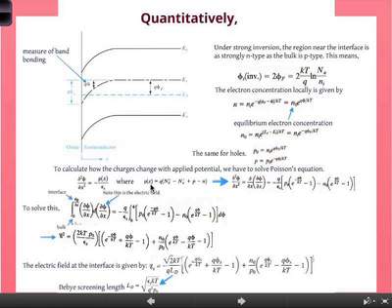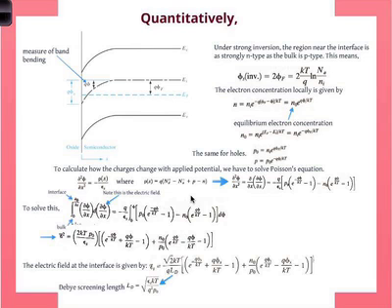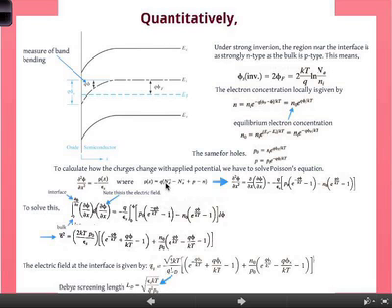Now we know rho is pretty straightforward to calculate because there are four terms: two positive terms, two negative terms. The charges from the ions, the acceptor ions and donor ions, if there are any. This is exactly the same as the first question in the midterm, for instance. You can go back and look at it. So you have the donor ions, acceptor ions, holes, electrons. Plug that in. Put everything in there.